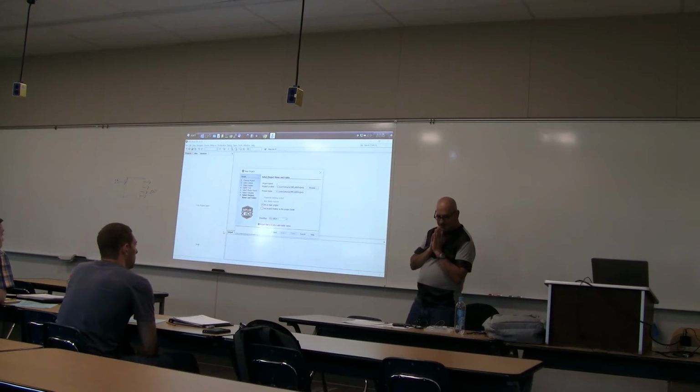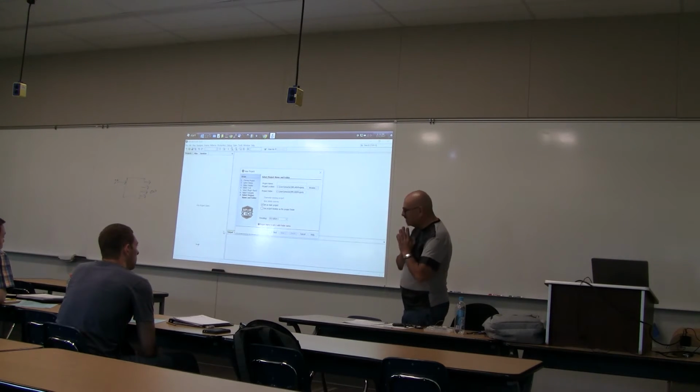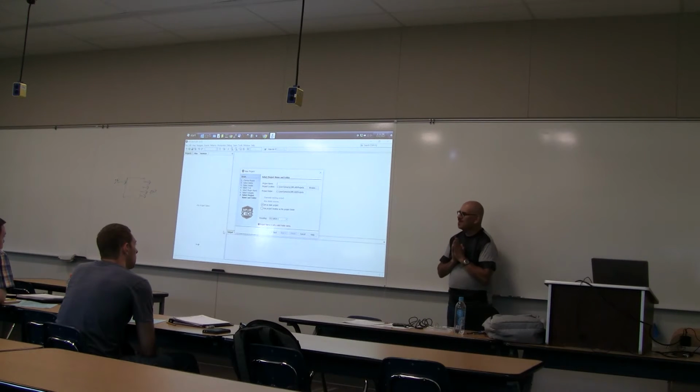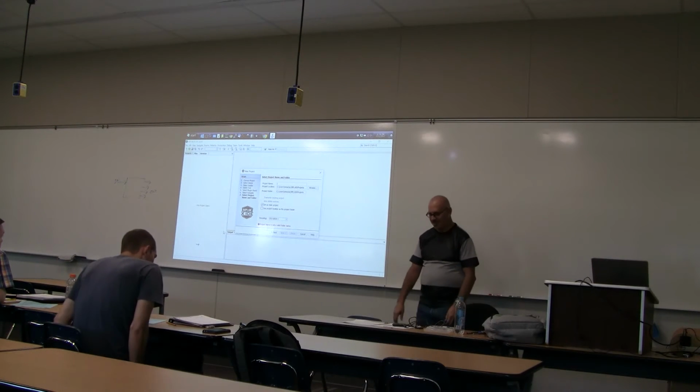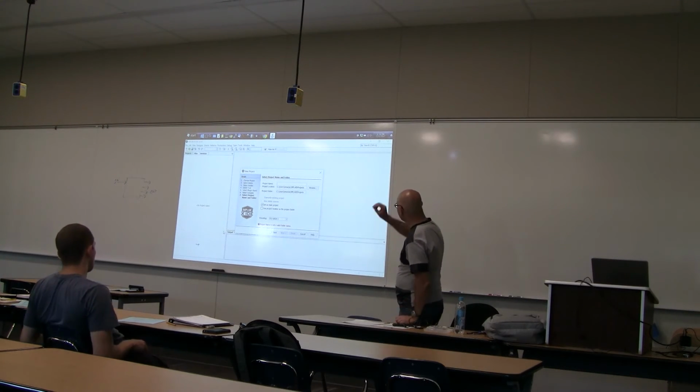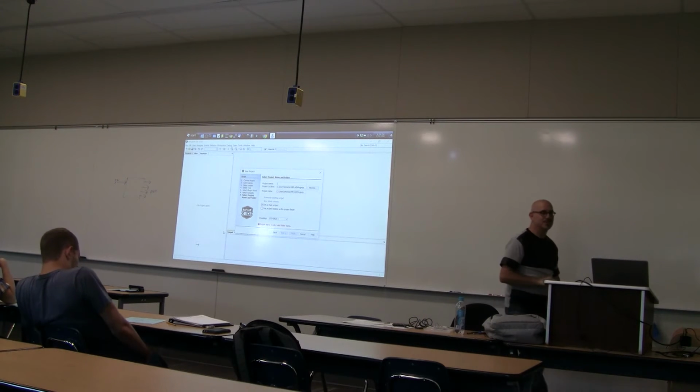One of the biggest problems that I've seen people run into is they're trying to get their chip to work and they keep making changes and nothing's working. And they keep making it simpler and simpler and they finally get it down to like a 2-line program and it's still not working. And the problem is the code that they were changing was not the code that was being loaded into the chip. Right? Because they had two projects mixed in the same directory. And it was compiling this program, but they were changing this program. That's why none of the changes they made seemed to have any effect. Right? But I've seen people spend hours trying to figure that out. So separate project for every piece of code you're going to write.